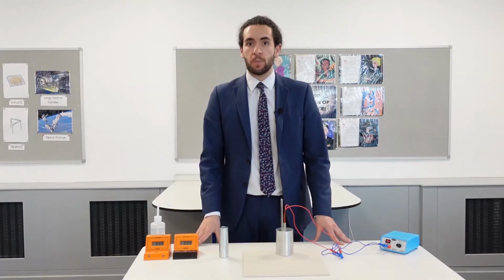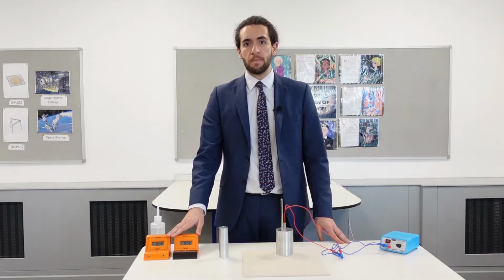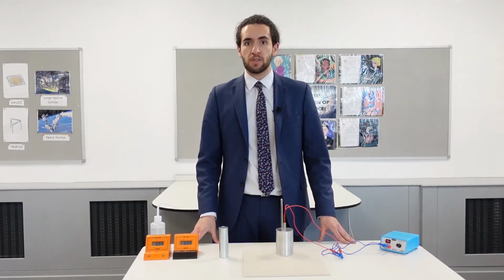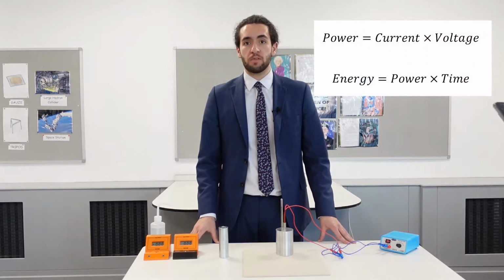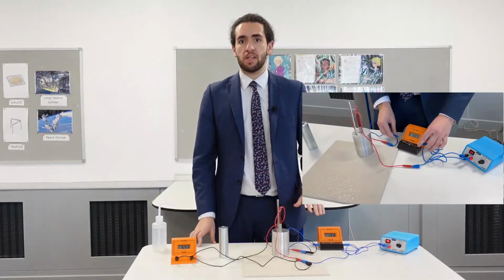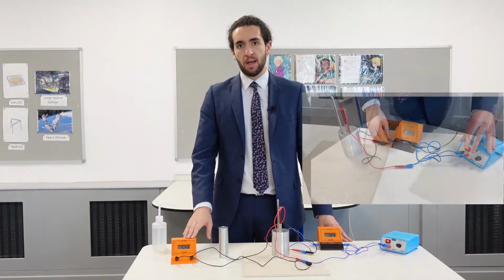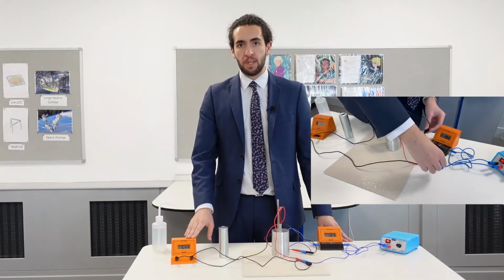If I can't find what the power rating is for my heater, then I can use an ammeter and a voltmeter, connect these up, and I'll be able to find my power rating by doing power is equal to current times voltage. Here you can see one series circuit with the ammeter and the heater, and finally a voltmeter in parallel.